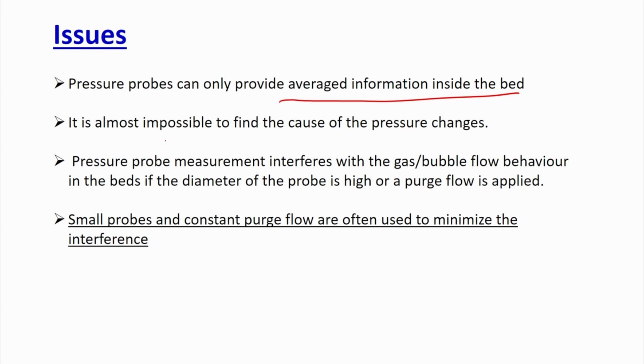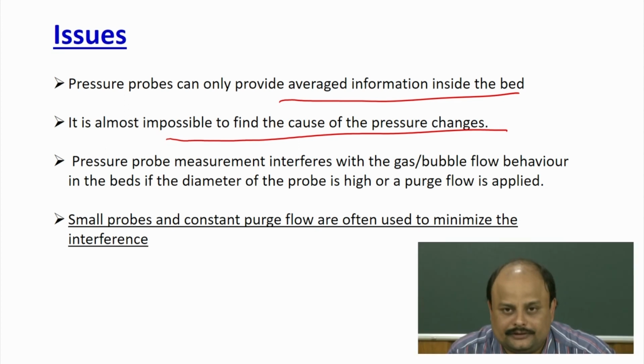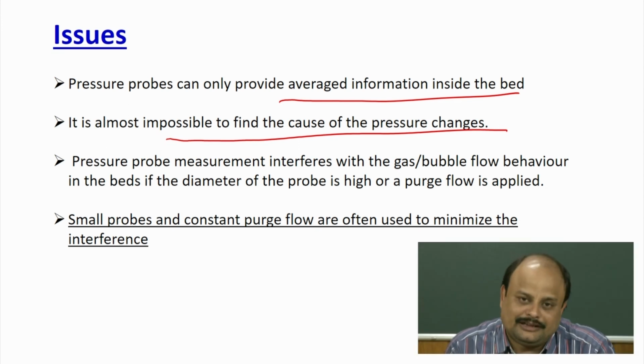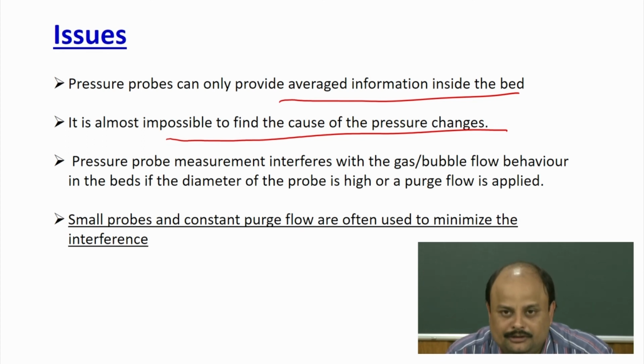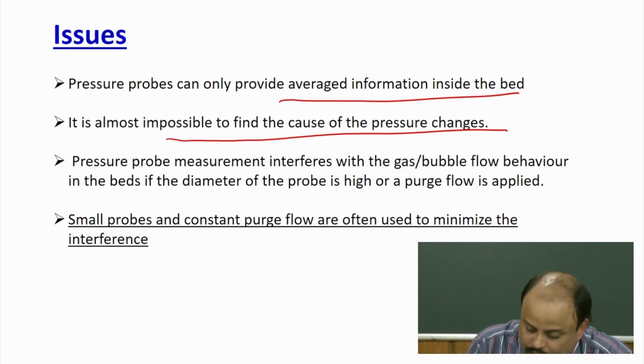Okay. That is what I said, that whatever you record shows that the pressure has changed, but it is almost impossible in multi-phase flow to pinpoint why the pressure has changed. Say in a gas solid system, if the pressure has changed, it can be because of the coalescence of two bubbles, breakage of a bubble, formation of some mesoscale metastable structures of the solids, say solid agglomeration and all. Pinpointing any region is almost impossible. Okay. So, that is there.